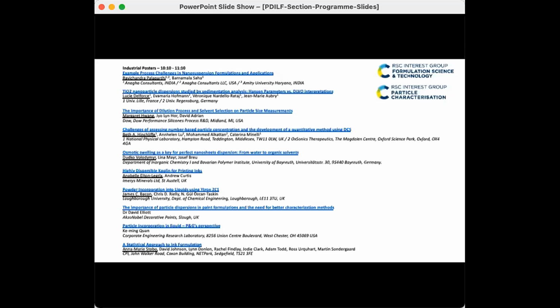It depends, obviously, on the printing technology. There's still the old technology, offset, which is very much used, so it's still very valid, and this is what this work was based on. That changes the way the kaolin and also the pigments are dispersed. The pigments are obviously very difficult to disperse, so there are some well-known technologies for these, like bead milling and triple roll mill.